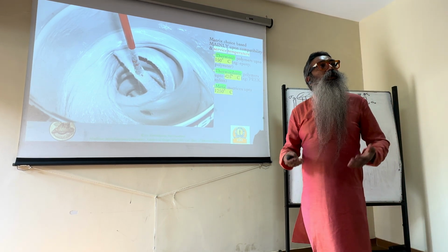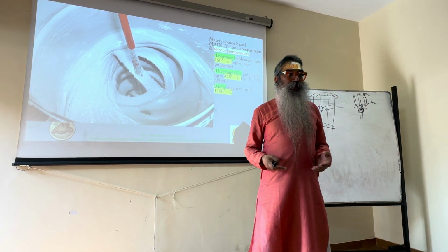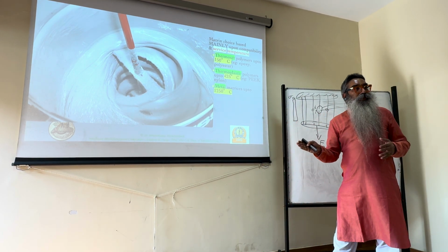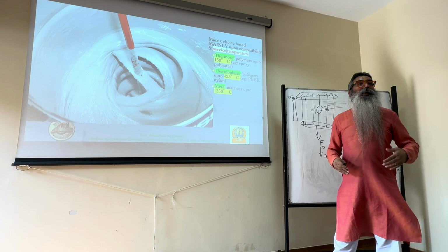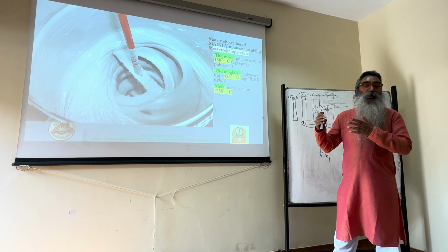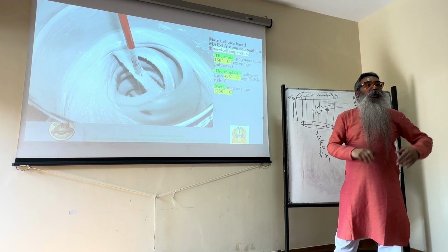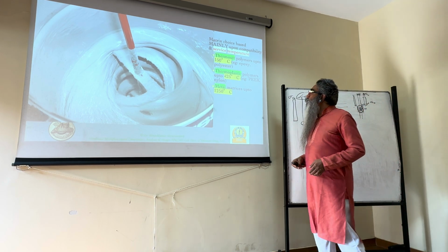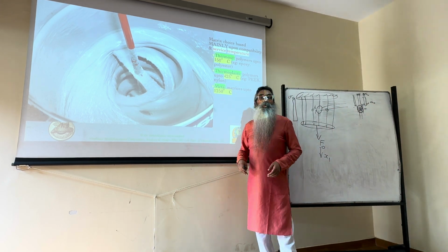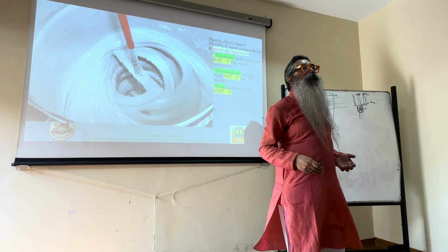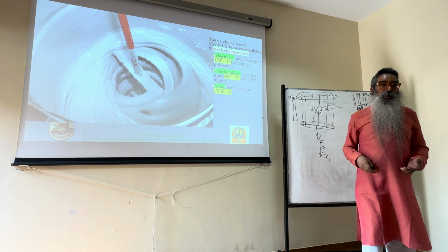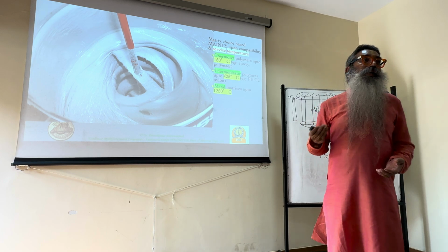Now you go for engine kind of applications, especially close to the combustion chamber, but in the frontal portion, like the turbine blades, or not the turbine blades, the compressor blades, or the turbofan in the fan itself, etc. Those portions you can probably have even higher temperature than 425 degrees centigrade. Then you have to go for metal matrices like aluminum, or more usually titanium alloys.